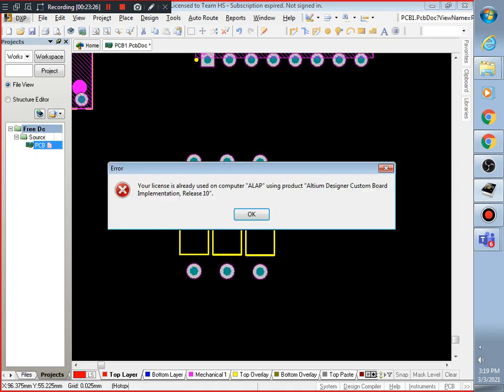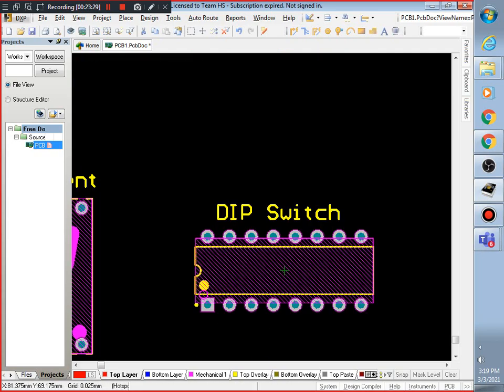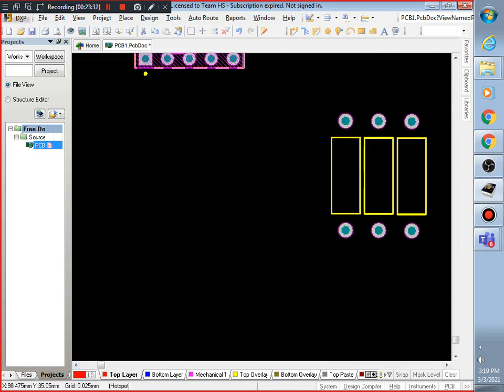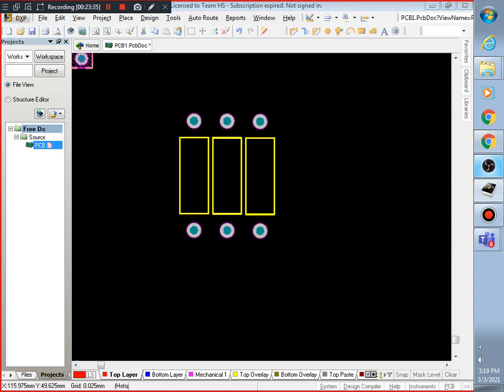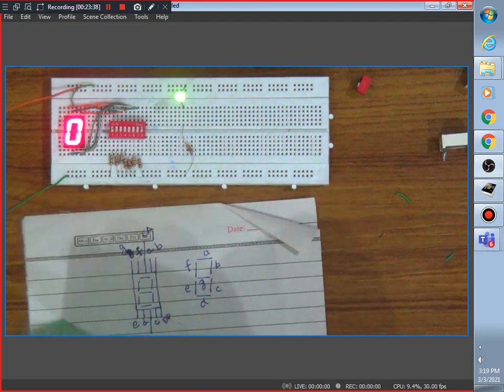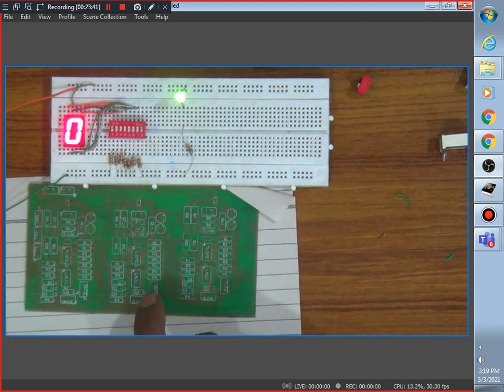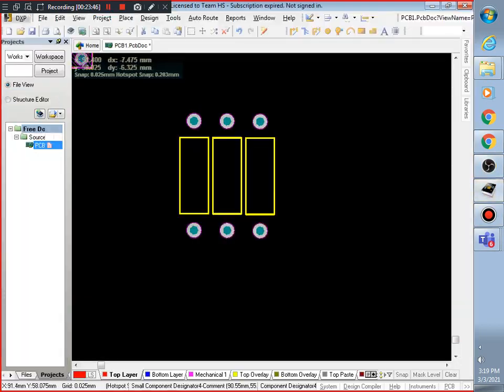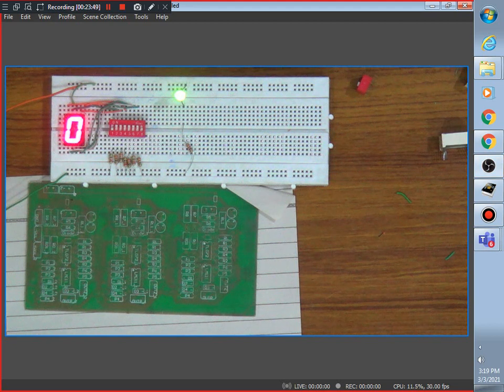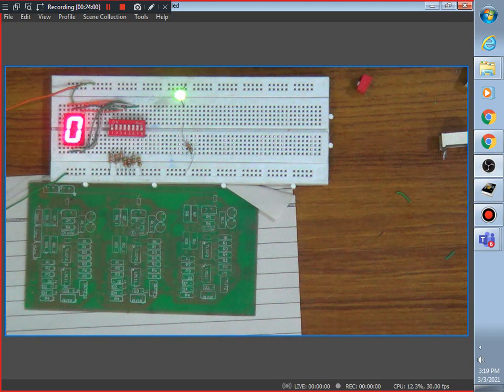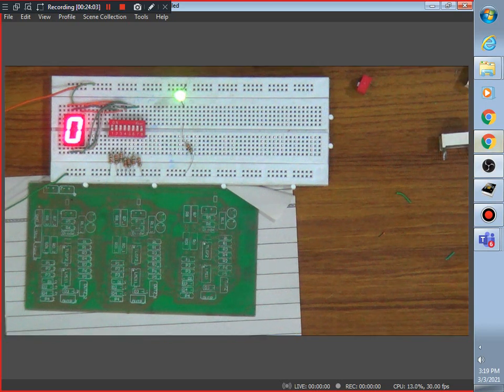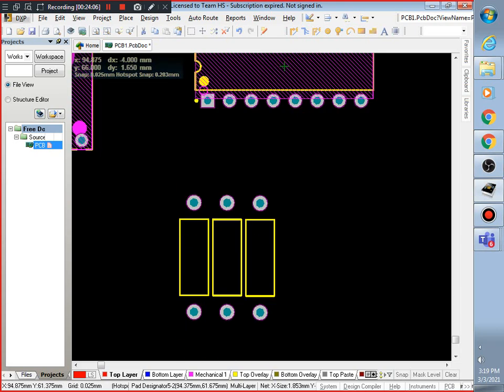Now these yellow color names which you are seeing over here, on this DIP switch and this 7 segment, are coming from the same thing which you are seeing on this side. This PCB, I told you in the previous class, has silk screen printing. So this yellow color marking is the same silk screen printing on this PCB top side. This tells the solder person who is going to solder which resistance or which component connects where. So now let me just see how I am going to place this one.